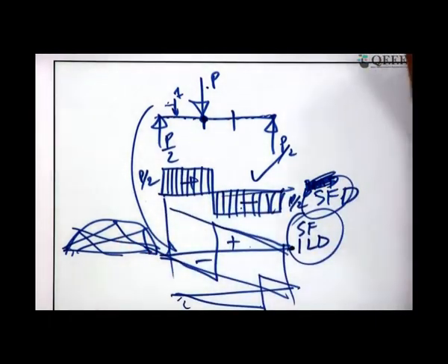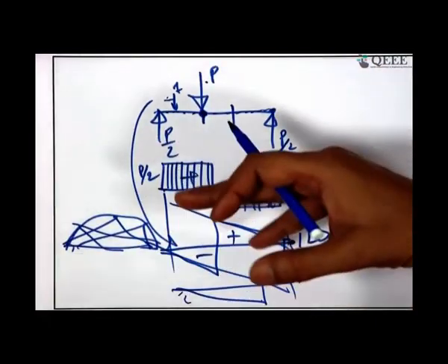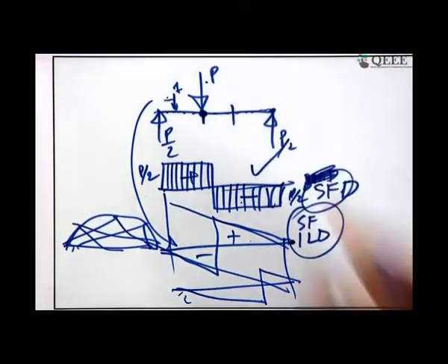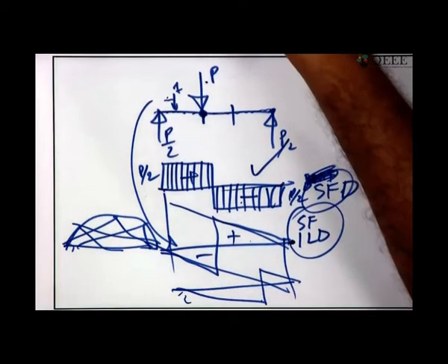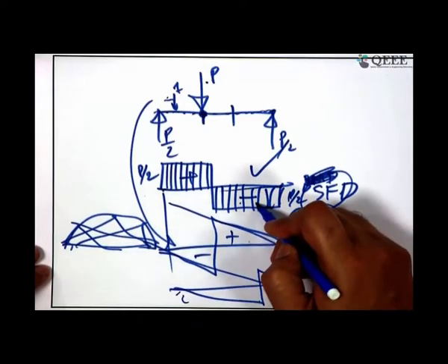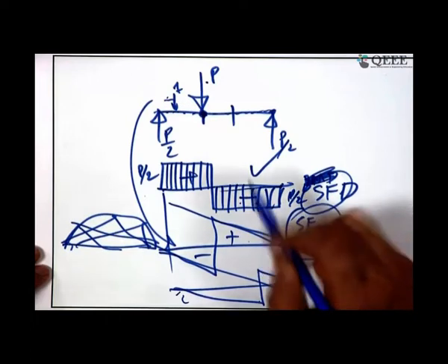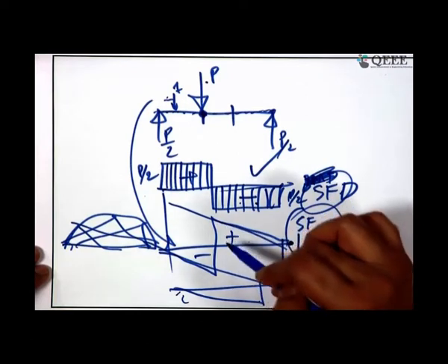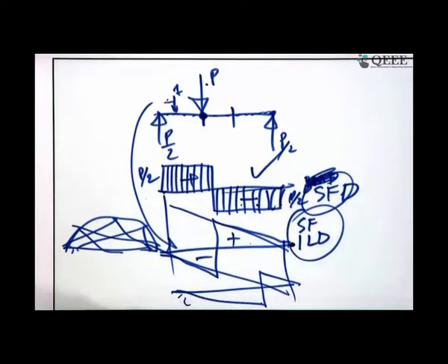I have not discussed this because these are not basics, these are derivative of that. Neither have I discussed in detail how the final maximum bending moment and shear force diagram should look. That I have shown you yesterday from one page of Professor Ramamrutham's book, I think. So, now that those things are not basic, you have to digest that this is spatial variation, the variation at a particular location with the unit load moving. You better train your mind like that and be prepared for further answering the queries.